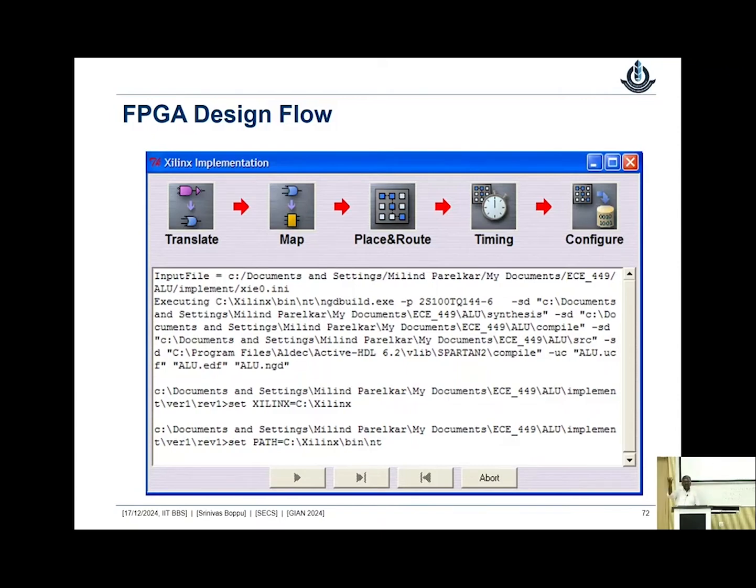Given that the FPGA contains LUTs, your circuit has to be really mapped into the LUTs. In an ASIC design, synthesis means you have AND gates and OR gates, so given a Verilog design, it has to be mapped into given gates. But here in the FPGA, what we have? We have LUTs and all. So given the Verilog circuit, I am generating a generic description. Now that description has to be finally mapped to LUTs. And if somebody has looked at the netlist generated by Vivado, you might have seen it instantiated many LUTs.